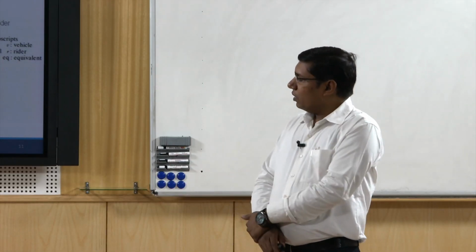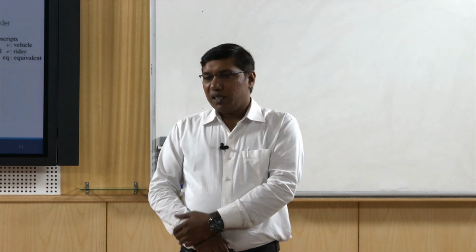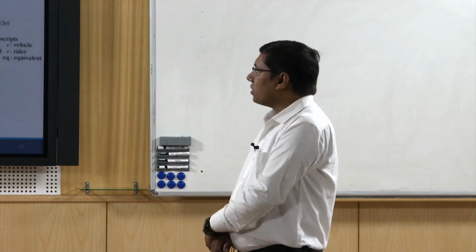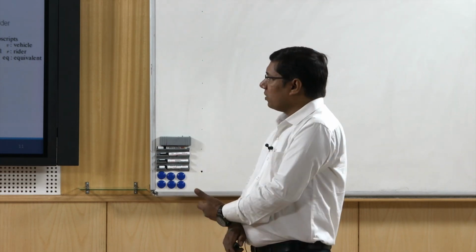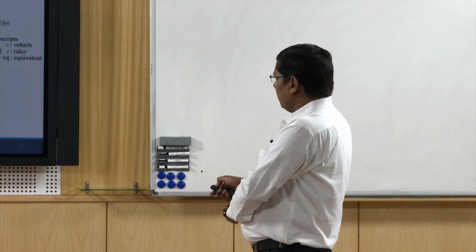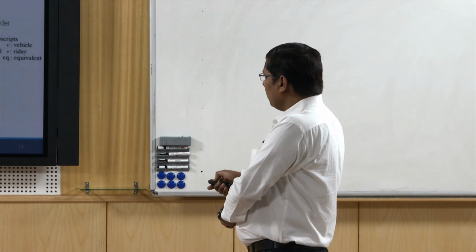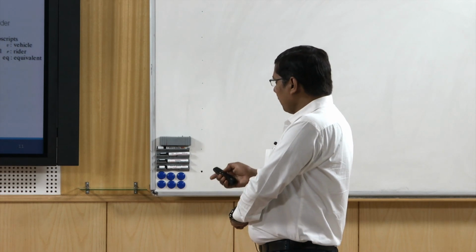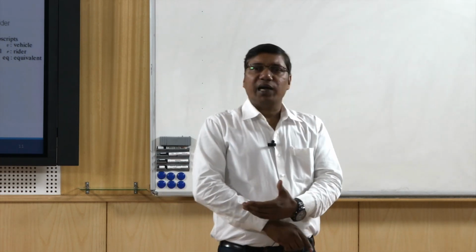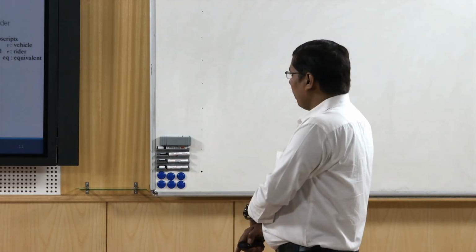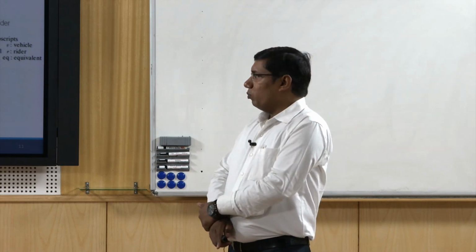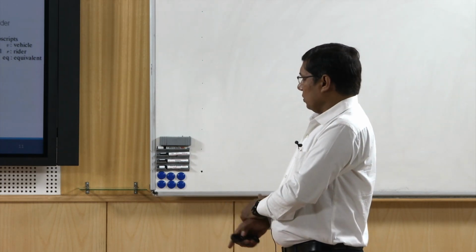and the degrees of freedom have increased, and of course in this case we will get the separate responses of each component, like we can get the response of the rider, the response of the vehicle, the response of the wheel. So this model will provide more insight, but computationally it is a more time-taking model.